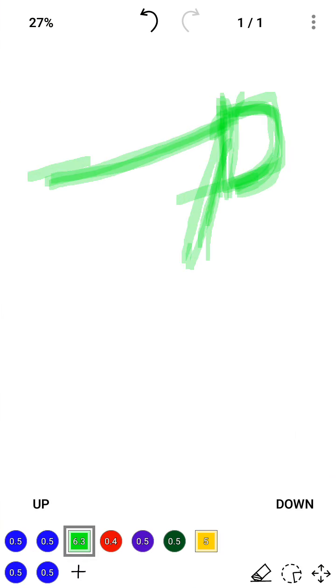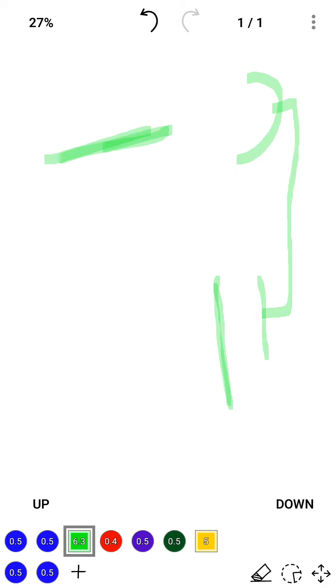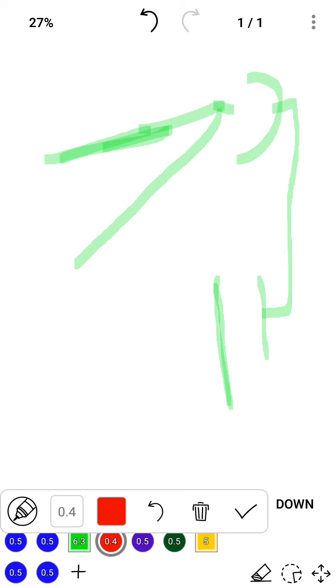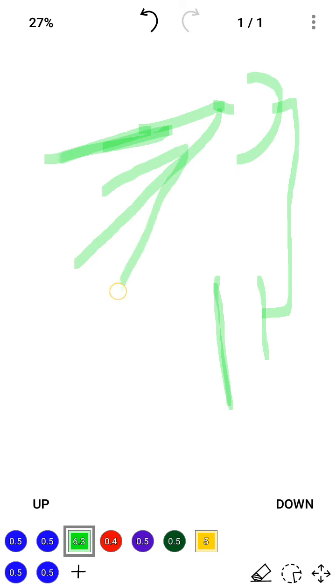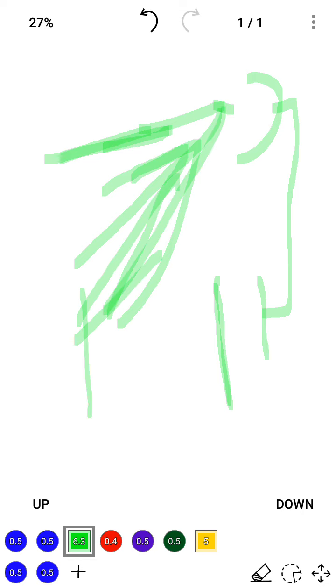Simply, this is the repeller, which gives a negative charge, and the electrons are also negatively charged. Accelerated electrons move up near it, and because the electron is negative and the repeller is connected to the negative terminal, they are repelled back. The earlier electrons that traveled in the negative half cycle have decreased velocity, so they move up and get repelled. They are decelerated electrons with reduced energy, and because of this process these two groups of electrons meet at one place and form a bunch, a group of electrons.